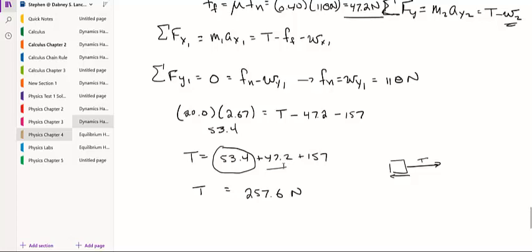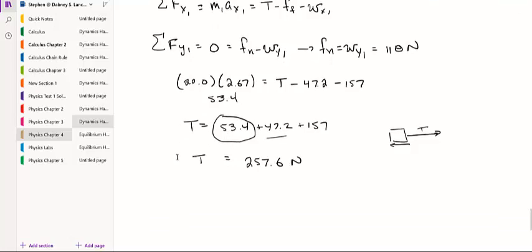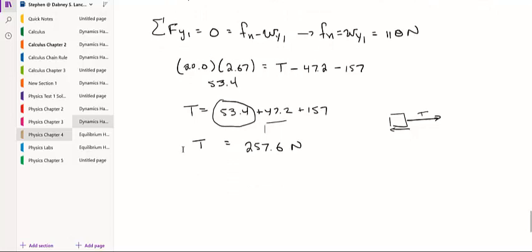This one is due to the friction force because it's moving, and this one is because of the inertia of the object. If you're on a flat surface, this part would be 0. If you were frictionless, this would be 0. If you weren't accelerating, both of these would be 0. If you weren't moving, if you're stationary, these both would be 0. If you were moving at constant velocity, this would be 0. Okay, you may have to go back and listen to that and think about it.